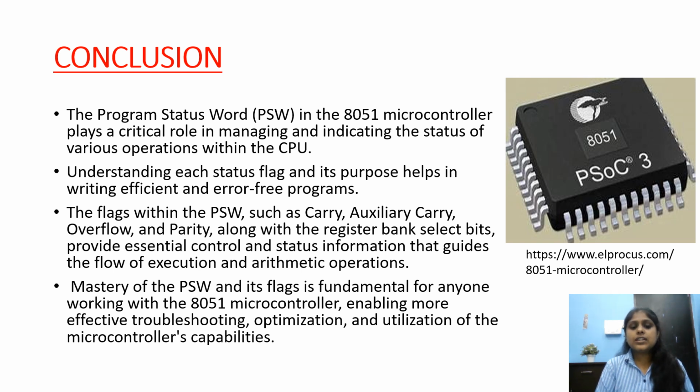The flags within the PSW, such as carry, auxiliary carry, overflow and parity, along with the register bank select bits, provide essential control and status information that guides the flow of execution and arithmetic operations. Mastery of the PSW and its flags is fundamental for everyone working with the 8051 microcontroller, enabling more effective troubleshooting, optimization and utilization of the microcontroller's capabilities.